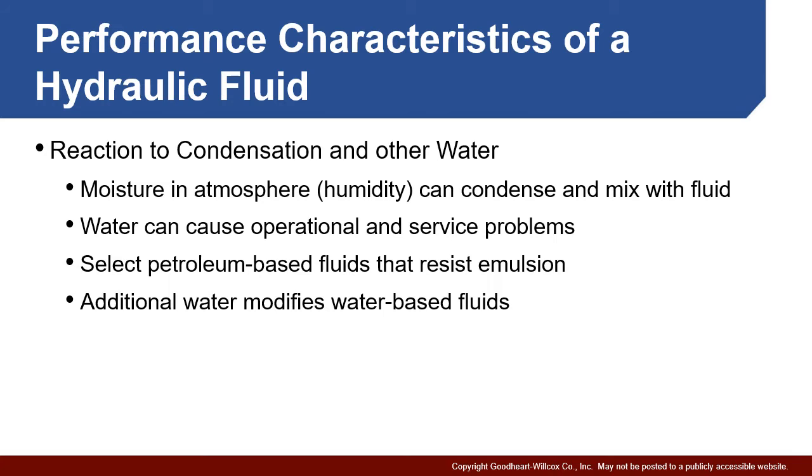While we're going to minimize the exposure of our fluids to water, the fact is it's nearly unavoidable in most hydraulic systems. Generally, we have open reservoirs, and it does interact with the environment. Fact is, even very dry air has some level of humidity in it, and when that air is exposed to heated and cooled fluids, it can condense into water and potentially mix with the fluid. This is a problem for a variety of reasons.